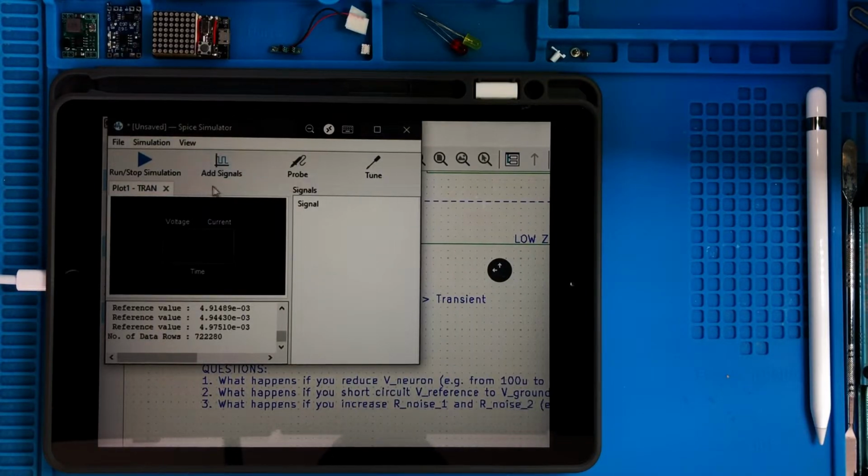So now what we can do is to attach a probe in our schematic. So the simulator, what did it do? It assembled a set of equations. If you remember, we did something similar when we were doing this node analysis during the theoretical part of the course. We tried to apply this mesh method in order to compute the voltage at every node of the circuit, and this is what the simulator did.